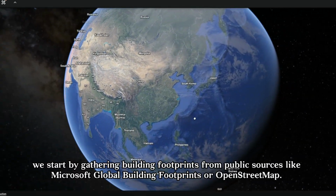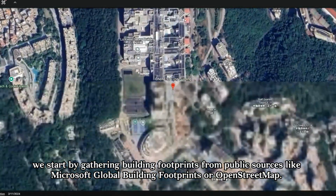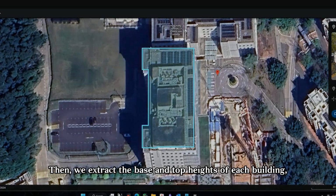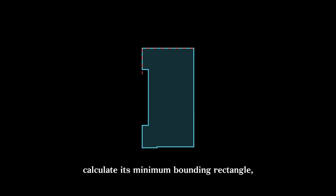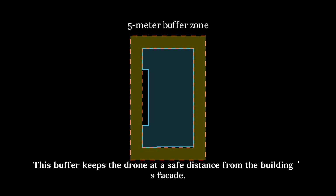In step 1, we start by gathering building footprints from public sources like Microsoft Global Building Footprints or OpenStreetMap. Then we extract the base and top heights of each building, calculate its minimum bounding rectangle, and create a 5-meter safety buffer around it. This buffer keeps the drone at a safe distance from the building's facade.